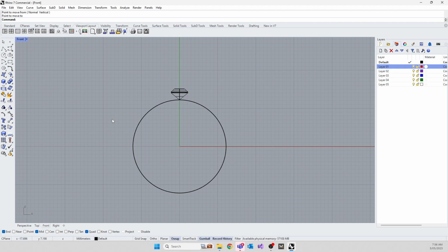And then similarly, if you wanted to rotate this, let's say you needed this item exactly sideways on this ring, on this quad, you can run the command rotate. Look at the command, where you want to rotate around, in this case the center of the world, so you can just type 0 and press enter. Okay. Where do you want to rotate from? From that quad. Let's turn off end for now. I'm going to rotate from that quad to this quad, and you've moved it exactly 90 degrees around the quads. All right. So this is what these guys do for you, the O snaps. You can also have a point.